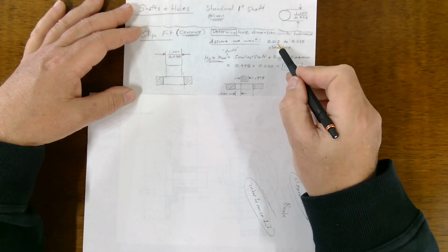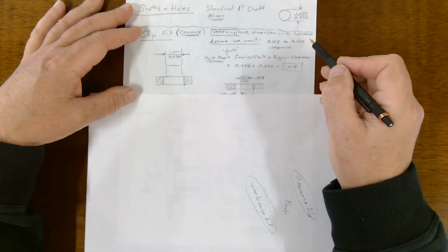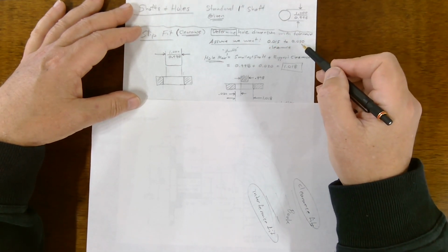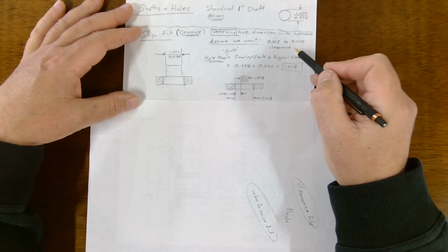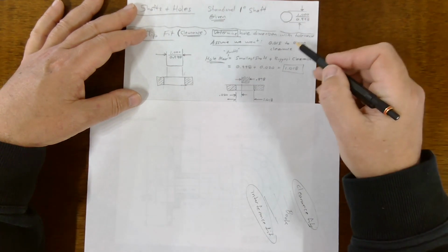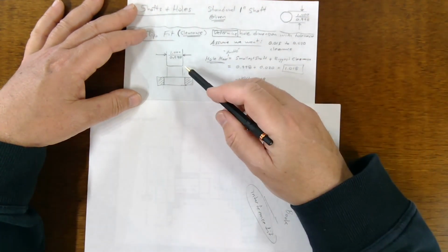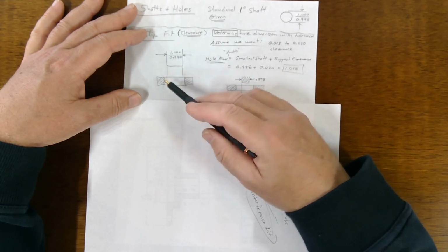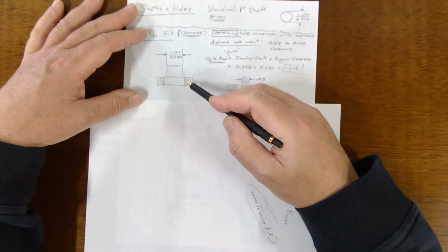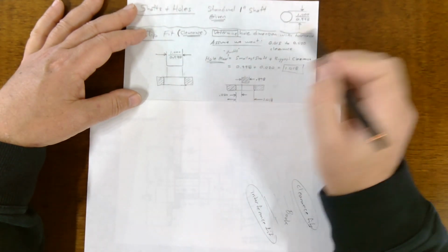So where did this 0.15 to 0.20 come from? It's just made up. Now, there's lots of reasons for different tolerances. It depends on what you're trying to do. Like, are you trying to squeeze oil in there? Do you want it to just barely fit? What are the rates of expansion of these materials? What's the lifespan? All kinds of factors, but that's beyond the scope of this course.